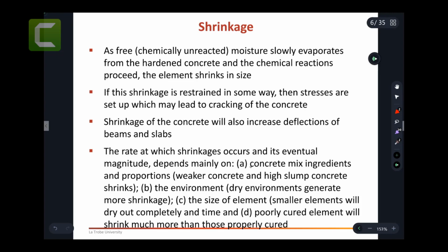So as we said, it depends on the mix of concrete to achieve the shrinkage strain parameter, the 800 figure that I was telling you. And the environment. Now, as we're going to take you through deflection and crack control over the weeks, you just need to have an understanding about what environments the concrete elements are going to be placed in.